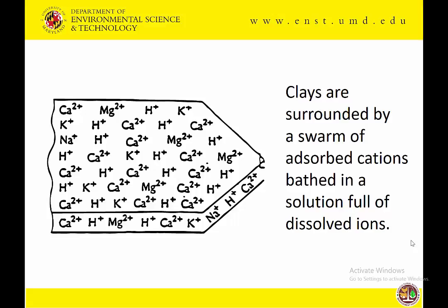You not only have ions, but each of those ions is hydrated. Right? So if you've got a lot of an ion in your system, like sodium, that has a big hydrated ionic radius, you can't get enough cations close enough to the surface that they're right against it. So in fact, there's a cloud of negativity around a clay, all right? A cloud of it. And the big thing is, how big is it? Because if it's a big cloud, you've got a problem. If it's a small cloud, we've got a process that can overcome it.